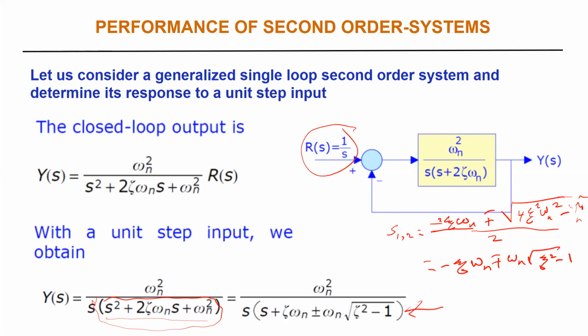But we didn't multiply the two solutions. You just put them at the right. No, look, what I'm saying is those are the poles of my system, and I want to discuss the location of those poles. I have a second order system, and the second order system will have two poles. So the s here in the denominator should have a subscript, which is 1, 2.